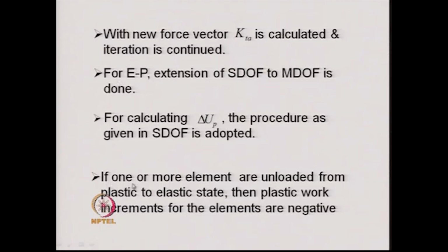If one or more elements are unloaded from plastic to elastic state, then the plastic work increments for the elements are calculated, and if they are negative, that means those elements are unloaded.